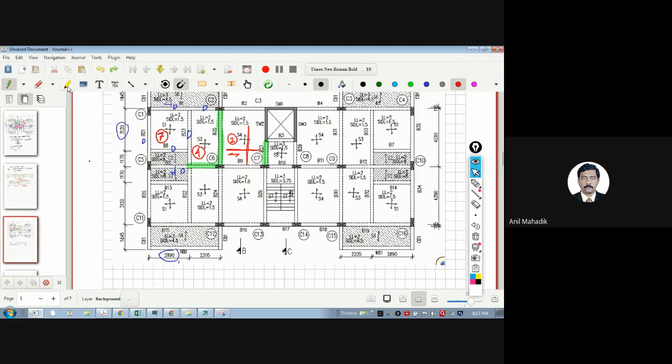Now again go to this point. Then here also, as this, now why I was telling. Now here this is my direction. This two-way slab. This direction is there. What is the direction of the staircase slab? This one. That means it holds good. So it is a continuous here. Again here it is a continuous. Is it continuous at B3 level? Yes, sir, it is continuous. At this point, is it continuous? There is no slab, so no continuity.